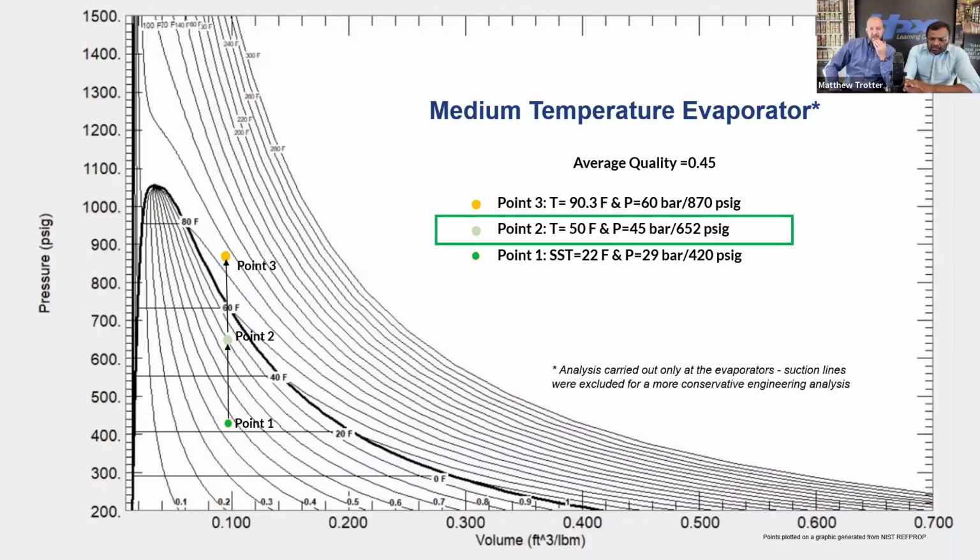So it kind of speaks to Rob's question. You had a great question that came in about when we're going to start using systems with high pressure ratings at the evaporators, when we're going to start seeing higher, 90 bar pressure rated systems at the evaporators. Well, we always want to do something with good knowledge and education and metrics around why we make these decisions. And when we look at this and see that in the low temp, we have to go this far to even get to a point at 40% of the charge.